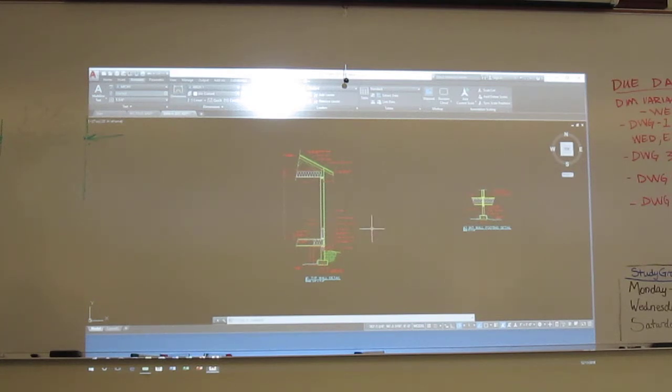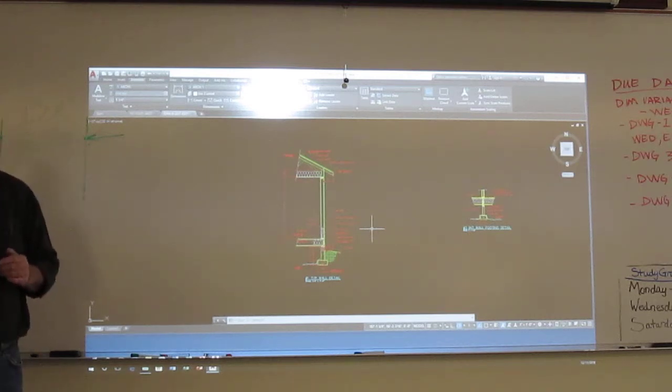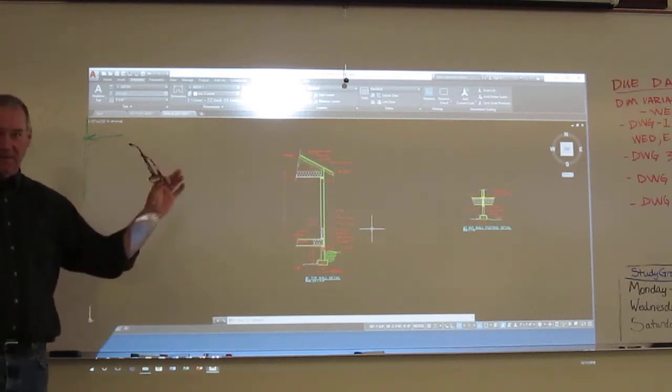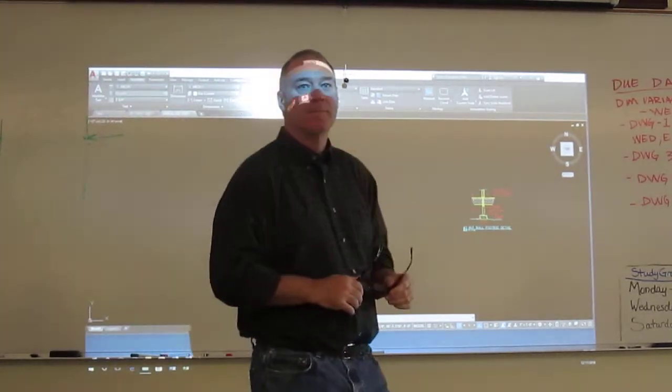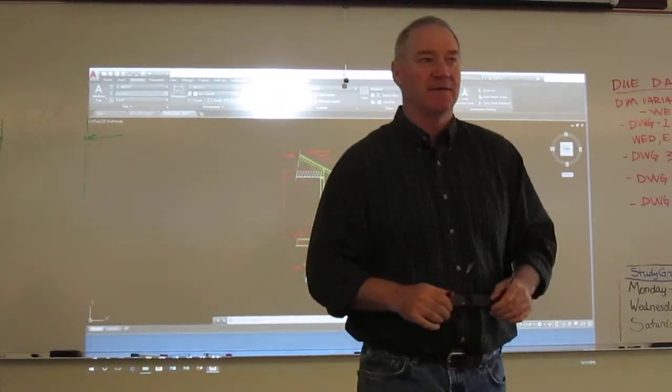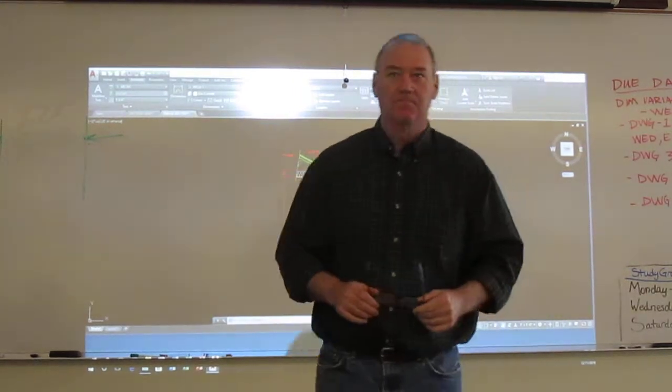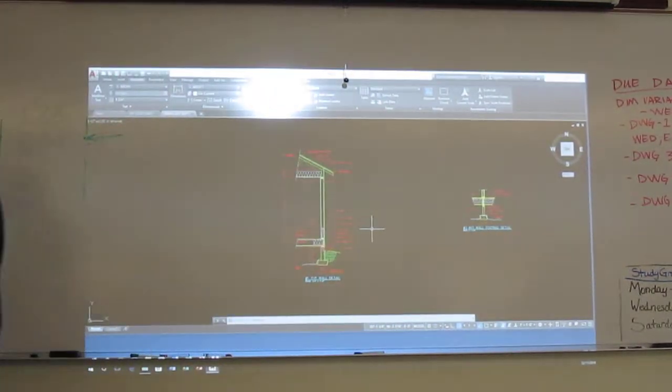We want to set it to 0, so... No, it's total preference. But the way AutoCAD's telling you what's XREF and what's not is by the transparency. When it plots, will it plot even if you have the transparency set to something else? Yes, it'll plot perfectly. Doesn't matter. That is correct. Transparency will have nothing to do with the plot. Yeah, it's just a display item.